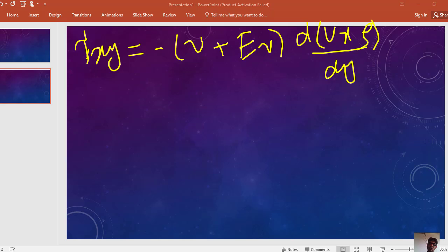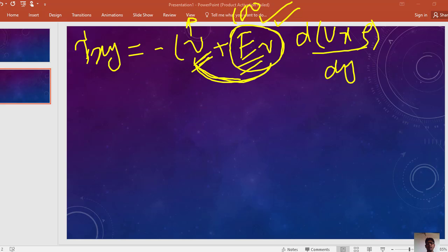So this diffusivity is for the turbulent flow and it is very high. It is 100 times larger than this molecular term. This is the molecular term which is on the molecular level, and this is for the turbulent flow. For the turbulent flow these two terms are combined. So for the turbulent flow, the momentum flux is denoted by this equation, suppose equation M.